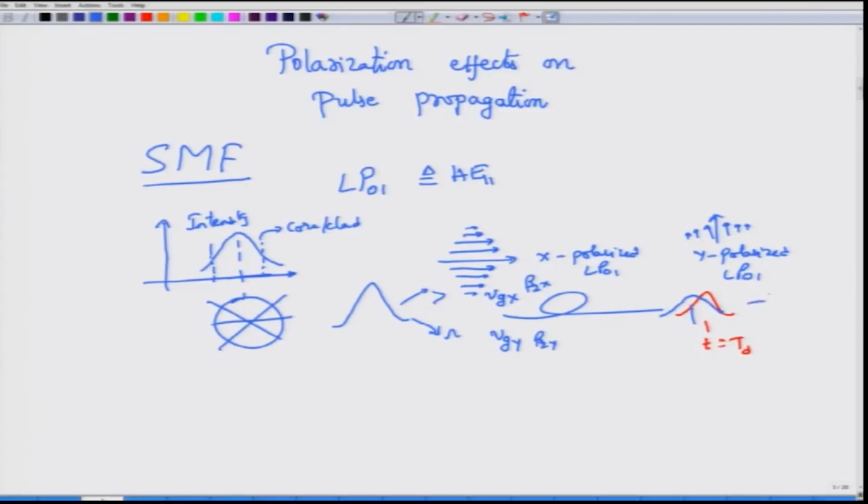But now when you put it through a detector, you want to detect what would be the output, since the detector is only going to look at E cross H, or E cross H conjugate, which if you remember is actually the Poynting vector, correct. And since you are considering scalar variables and transverse coordinates, what this actually means is that you are looking for |Ex x hat plus Ey y hat| magnitude square, and when you do this magnitude square, the detector which is actually doing this cannot detect the fields, it can only detect the power. What it actually detects is this combined pulse which would then be looking like this, right.